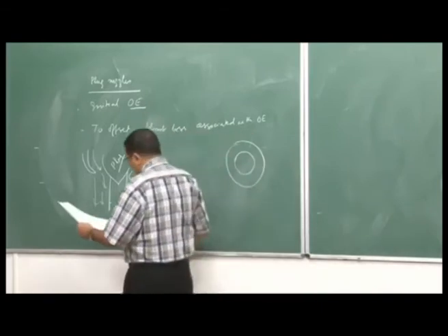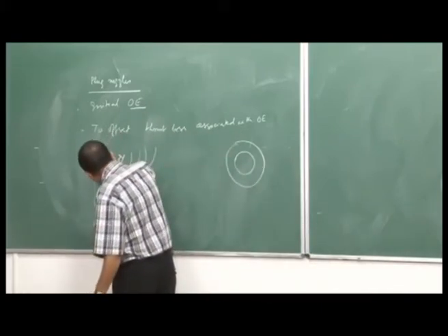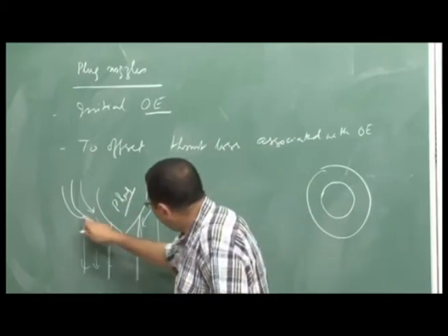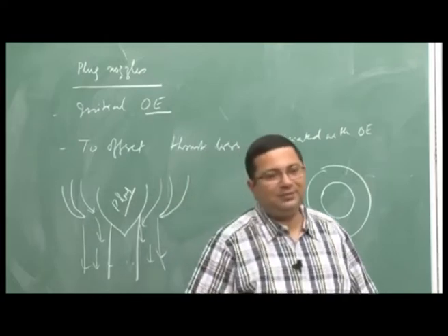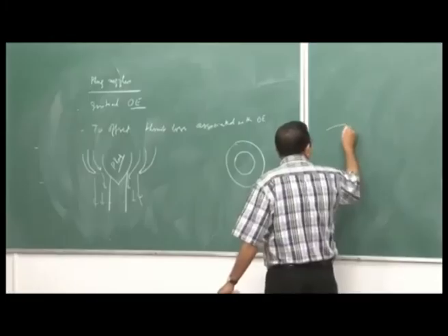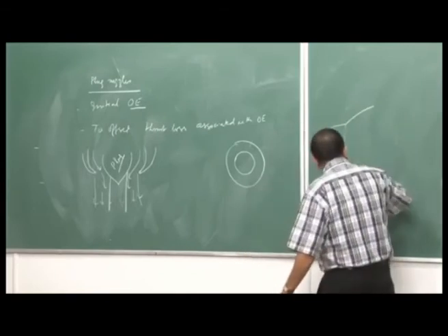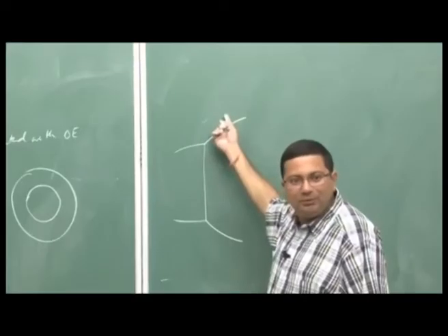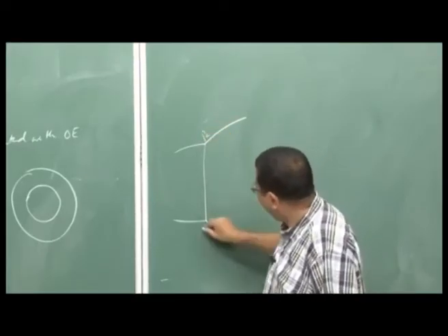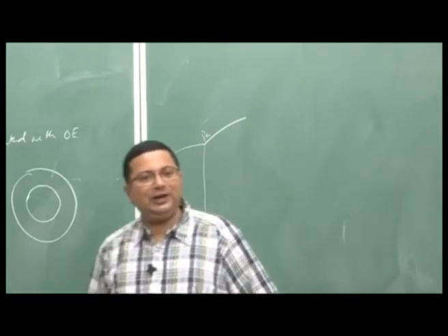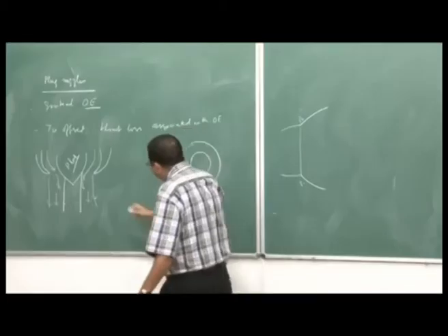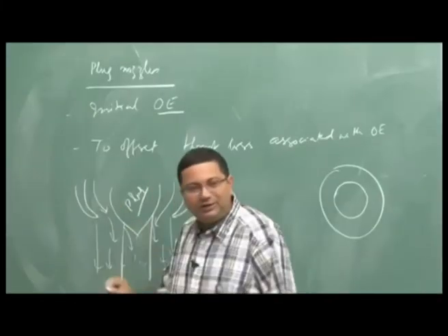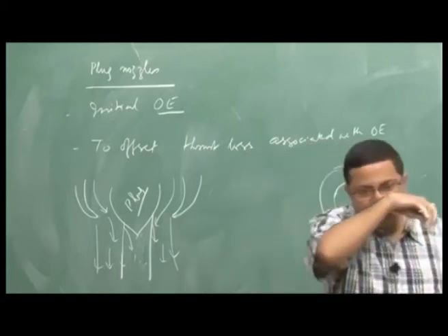And what we have is, we have two corners here and here, and these two corners are not at the same location. Okay. Now, when I drew this, there was a jet boundary, right. Here at the edge, it is equal to the atmospheric pressure, it was equal to P A. So, at the corner, it will take the atmospheric pressure. So, here also then actually like this, it takes the atmospheric pressure because of the presence of this plug, and